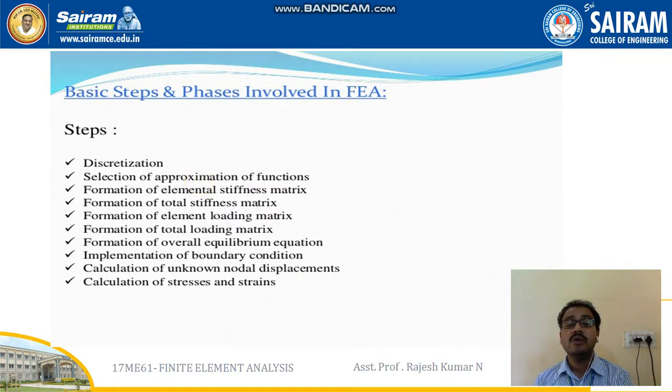The major unknowns in structural analysis are the nodal displacements. If in your discretization you made 6, 7 or 8 elements, each element has its respective nodes, and for all of those nodes it is possible to find the nodal displacements.